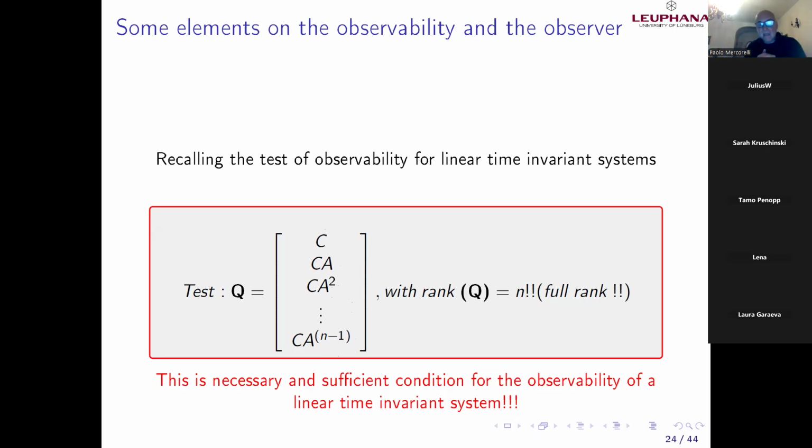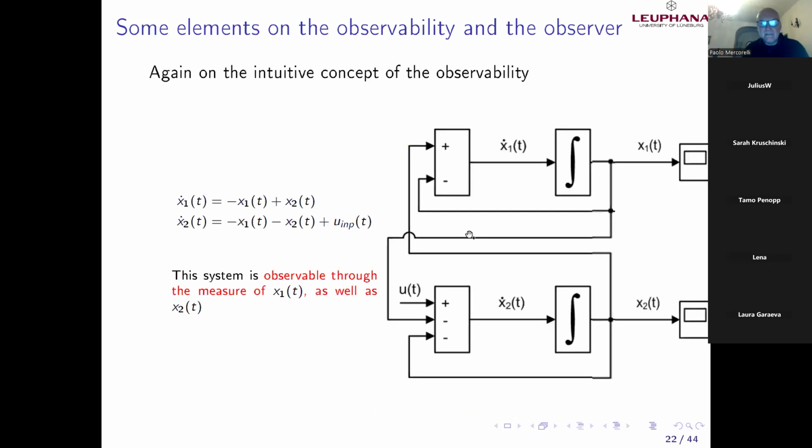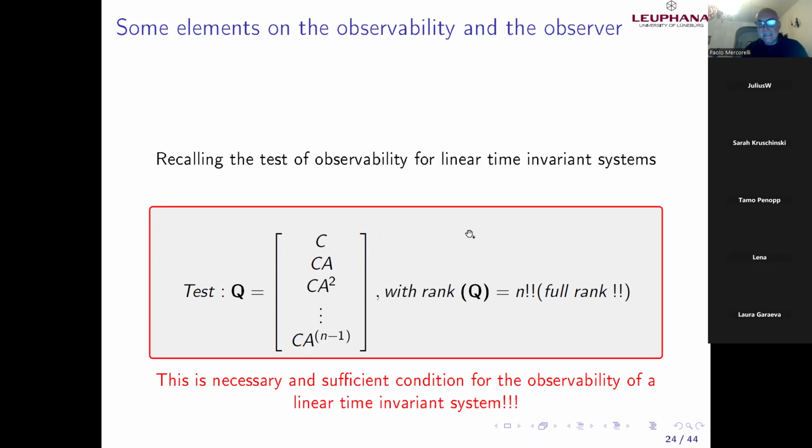I don't have time, but believe me. Why did I stop using just two rows, C and C multiplied by A? Because, very important to clarify now, the last row is C multiplied by A to the n minus 1, in which n is the order of the system. It's a shame I was not precise, at least before. I don't remember if I told you about n.